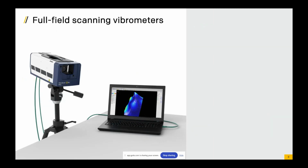Okay, now talking about full field scanning vibrometers. The difference between the previous type and this type is, like I mentioned, that they have steering mirrors. And on the screen of that laptop, you can see an example of a result that we might get. So say that was a beam, and the beam were to vibrate, then we can map that vibration across the surface at a given frequency or over time, and then see the resulting animation as an exaggerated version of that vibration.